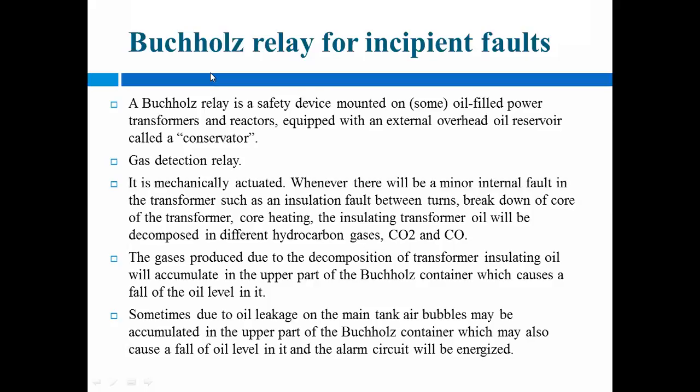Sometimes, due to oil leakage on the main tank, air bubbles may accumulate on the upper part of the Buchholz container. This also causes the oil level to fall, and the alarm will be energized.